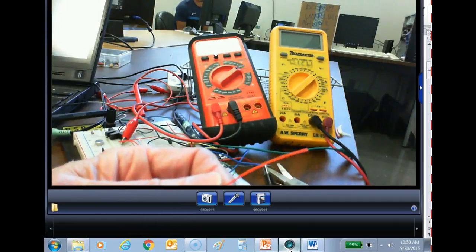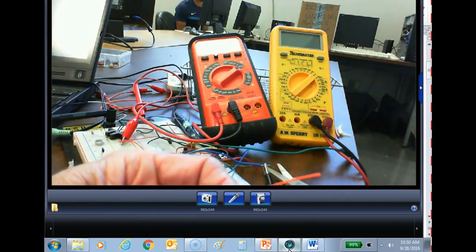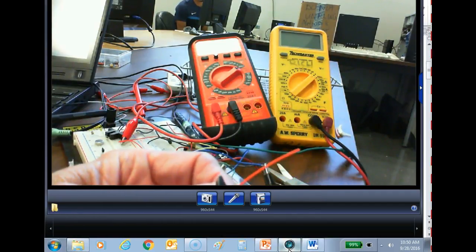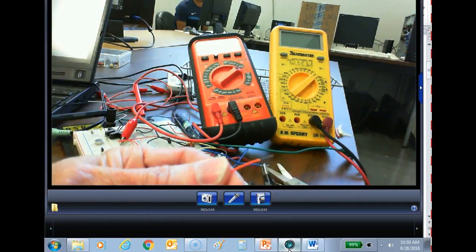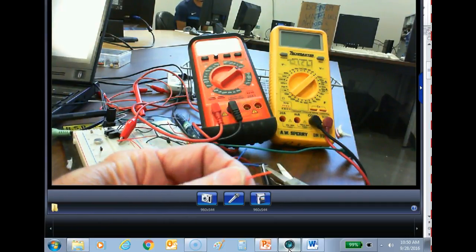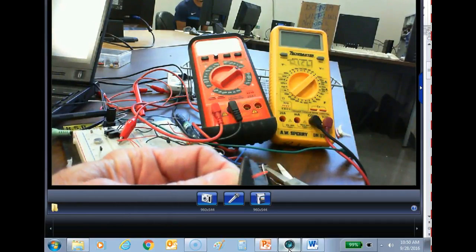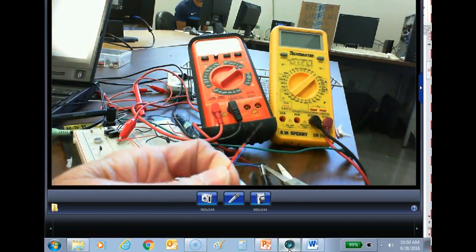Now what you need to do, this is glass. So if you have to strip off a lot, what we recommend is you do it in about 1/4 inch increments. So instead of trying to strip it all the way down from here, you come up here and strip off right there. Understand? You go about 1/4 inch at a time till you get it to the length you want.